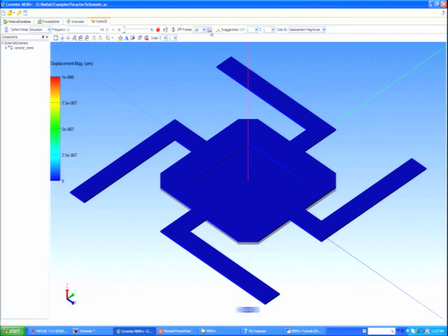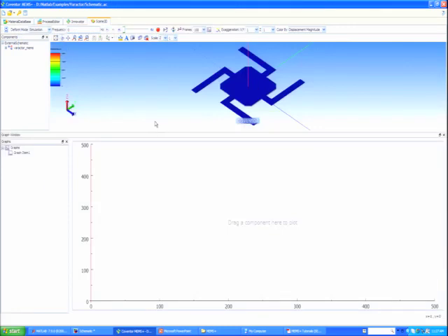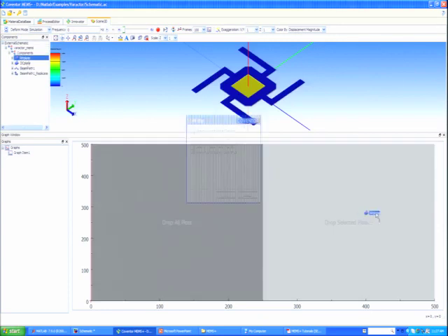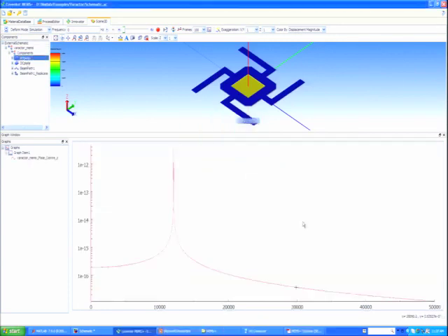I'm going to bring in results from MATLAB. So I have this 2D plotting window here. I'm going to say plot for me the center of this plate. How does it move? And there's your characteristic response curve. There's no damping in this device. I've not put that into this. I've got some damping in the transient analysis, so we'll see the thing oscillating and dying down. But this is a simple AC response of the device. It looks like it resonates at somewhere around 12 kilohertz, a little under 12 maybe.